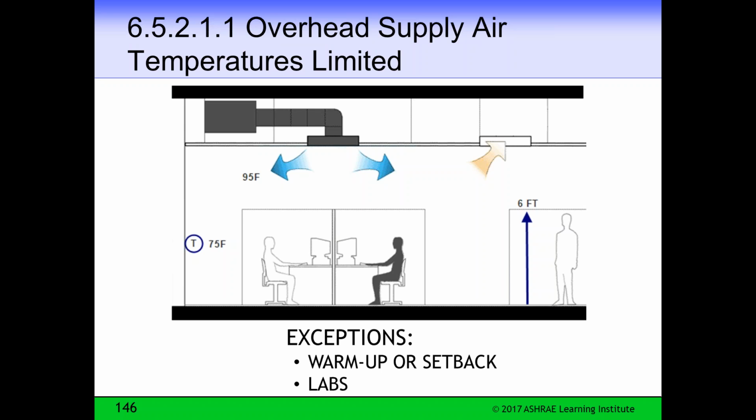We thought the buoyancy of the air was a good point, and for good energy savings and a good mix, we put a 20 degree difference. So a 75 degree thermostat set point, which would be very hot in the winter, would be a 95 degree supply. If you used 68 or 65, you can see you would be at 85 or 88 degrees supply air temperature. And then we have no other requirements.